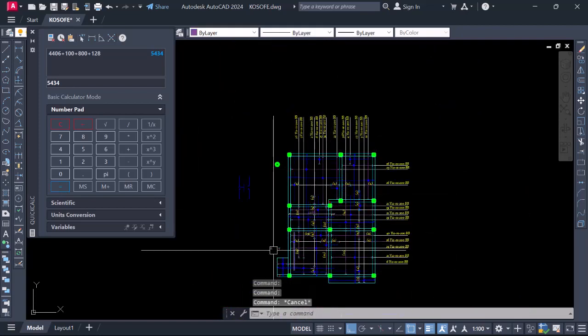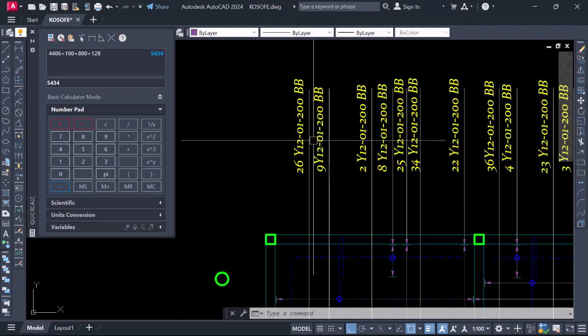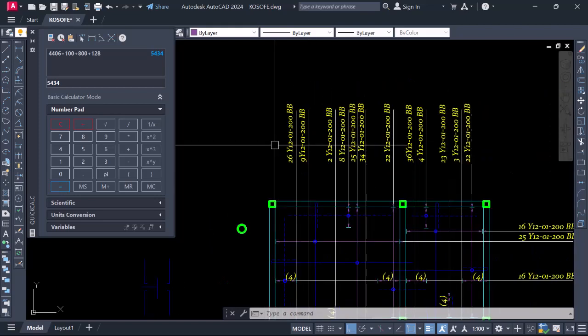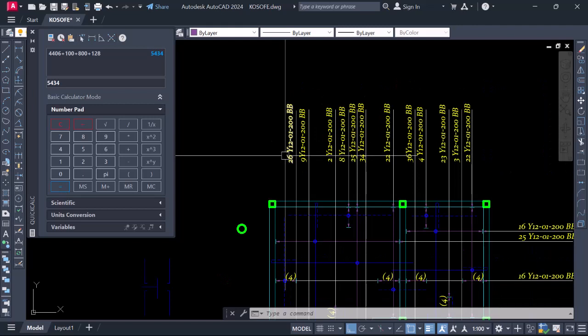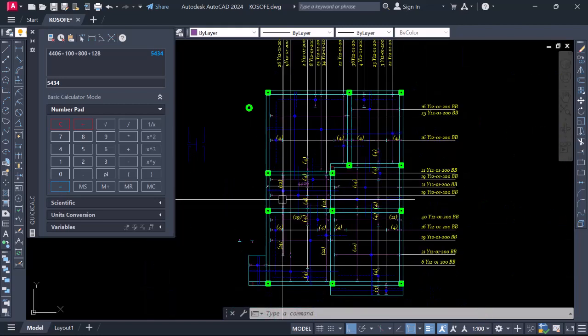But aside from this, every other reinforcement here has a different shape and length, and they mix each of the figure. For them to have the same bar number, before I continue, they must have the same property of these three specifications: the same shape, the same length, and the same size. All right. So in this specification, in this regard, let's go on.